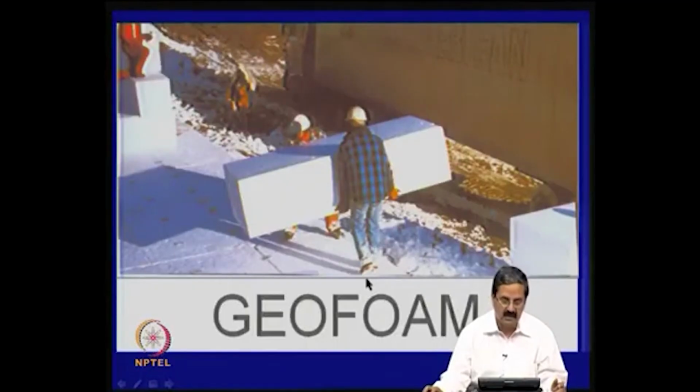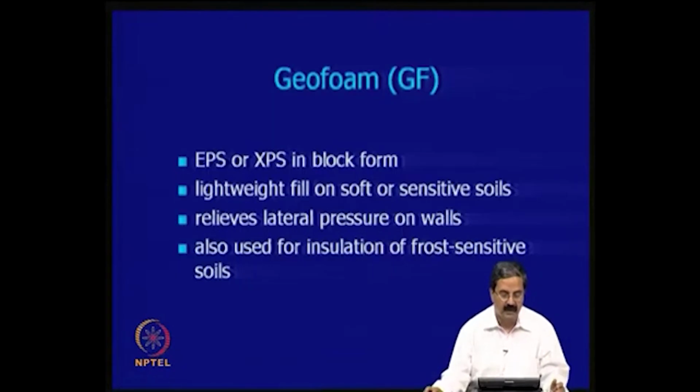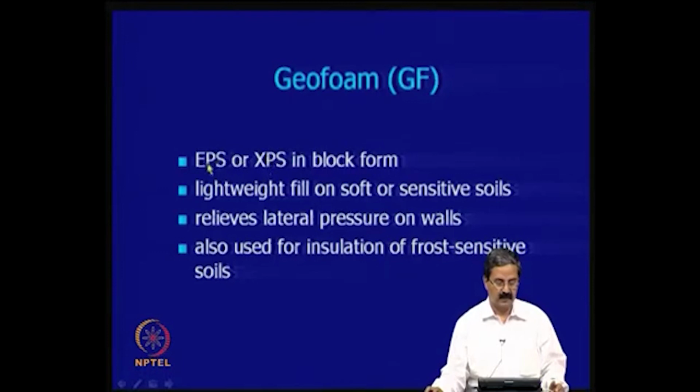There is another thing that is called geofoam. It is another interesting material which is very useful in many applications. It is a foamy material. It is a very lightweight fill on soft and sensitive soils, and relieves lateral pressure on walls.